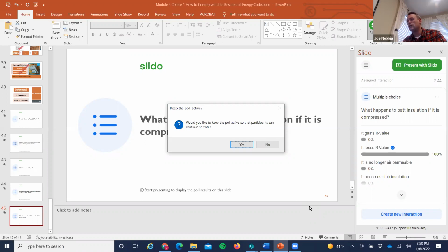So a lot of the code is stuff that, as I mentioned at the beginning, it's just things that are required. It's in the installation instructions already. We should be doing it this way. And they're meant to make sure that our insulation is actually going to function once we install it correctly in the wall. And it really is something that if the inspector has the time and takes the time, a lot of houses are going to fail because it's done incorrectly, and anything from compressions to voids to all sorts of other reasons can fail you.